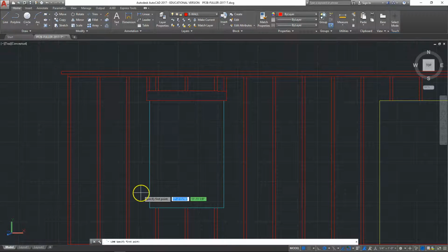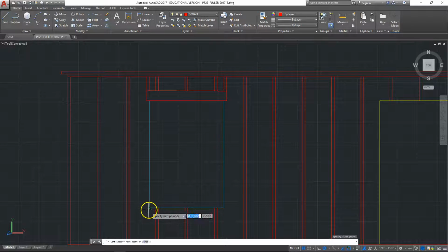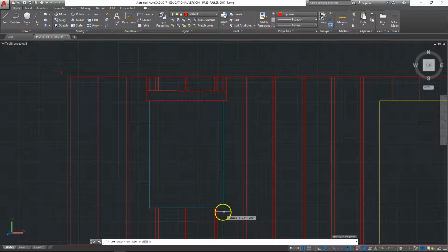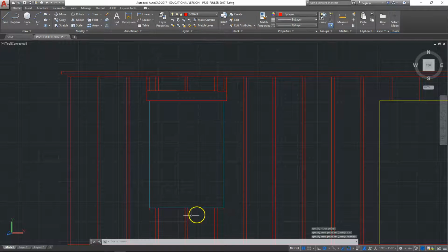At the bottom of the window, create a sill with a standard 2x4. Use the same technique as you used on the header to establish ends that extend an additional 1.5 inches in both directions. Connect the two lines horizontally to each other and trim timbers that fall inside of the rectangle.